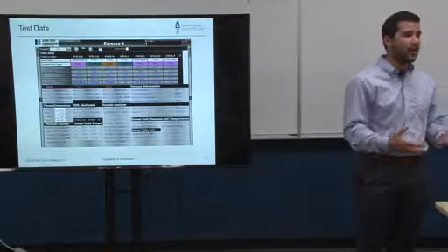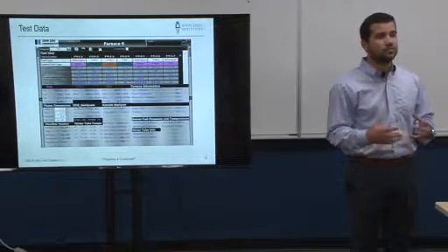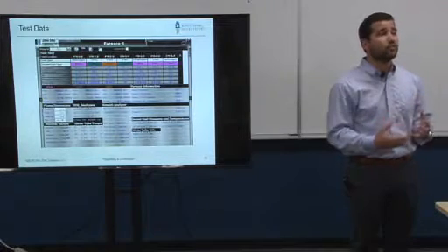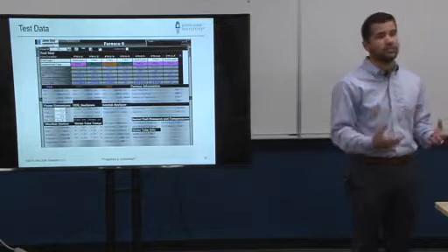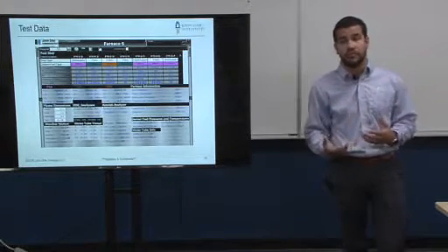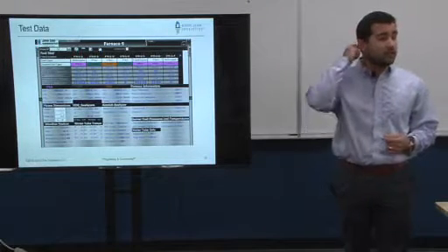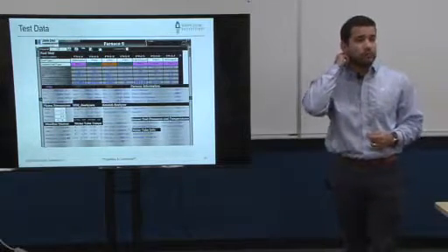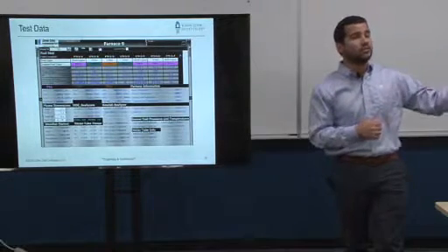We understand that NOx production in this particular application is predominantly happening due to thermal NOx, right? So the NOx is being created because of the added energy of the surroundings or the energy of the combustion itself. And so matching that furnace temperature is very, very important when it comes to burner testing and to predicting emissions in the field.